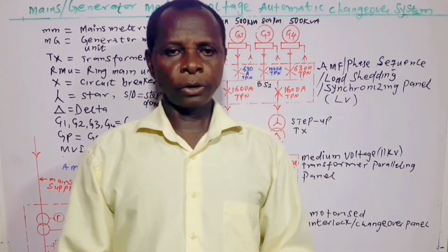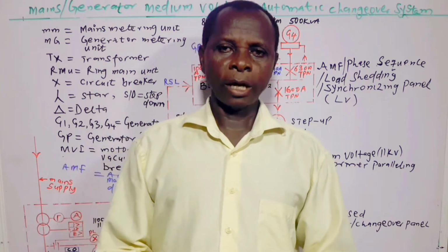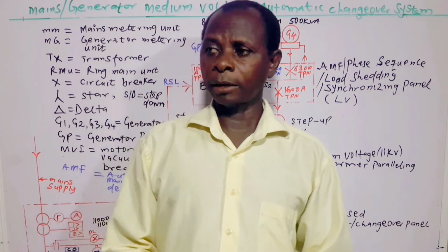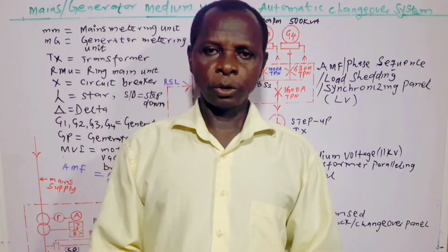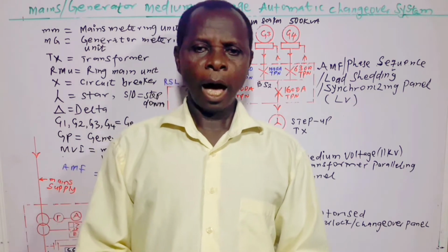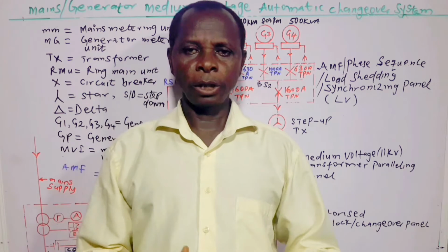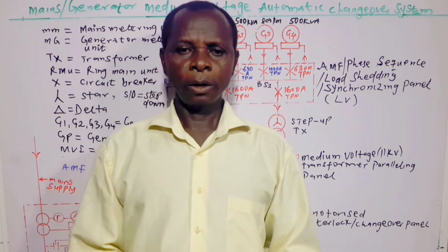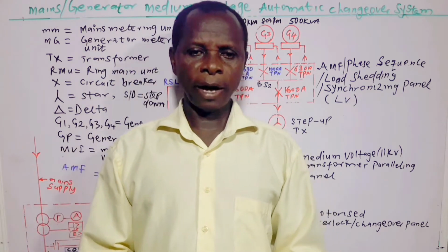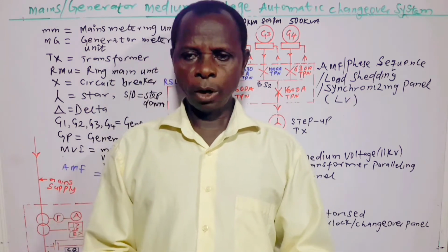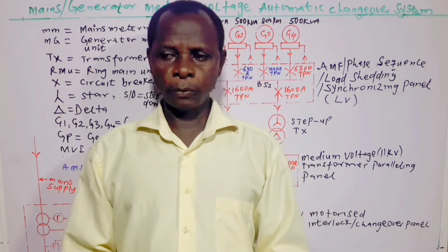In two of my videos recently uploaded, namely high tension transmission, that is transmission at high voltage and low current, and also power distribution at medium voltage, I talk about the effect of voltage drop, as it could make the designer or the engineer prefer making use of medium voltage such as 11 kV or 33 kV instead of low voltage.